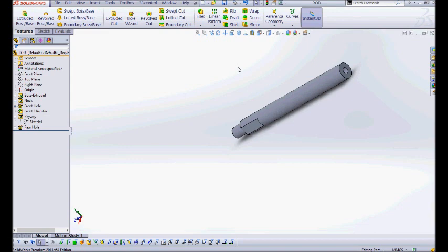And because we've added that neck, we really want the keyway sketch to start on this face. So remember, I think someone asked me, can you move a sketch from one face to another face if you accidentally pick the wrong plane or the wrong face? And the answer is yes. You can redefine your sketch plane.